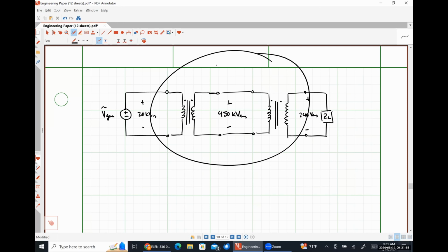All of that could be prevented if their main breaker was thrown so that their home was disconnected from the utility lines. But a person that buys one of those cables isn't smart enough to realize they need to turn their main breaker off to make sure that they're not backfeeding their entire neighborhood. So anyway.